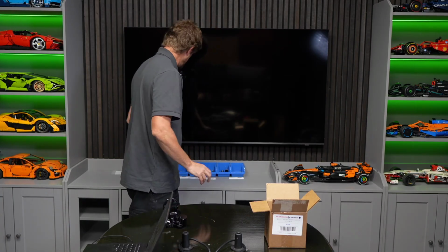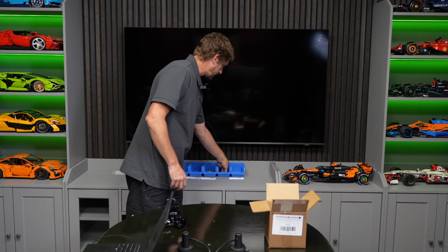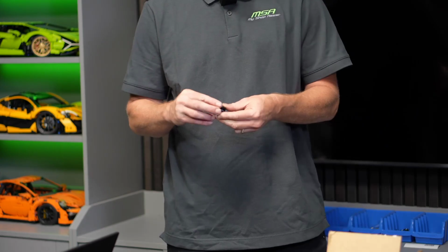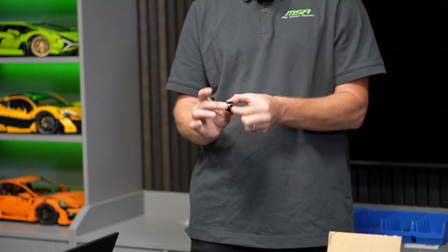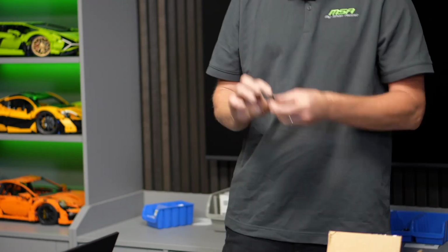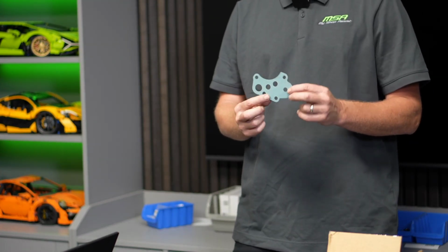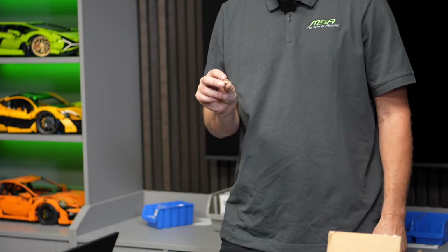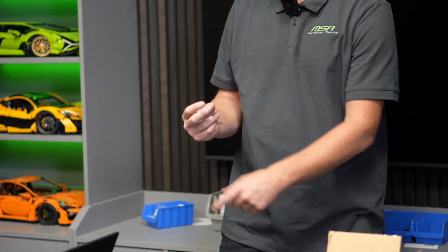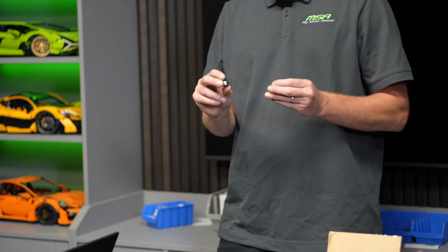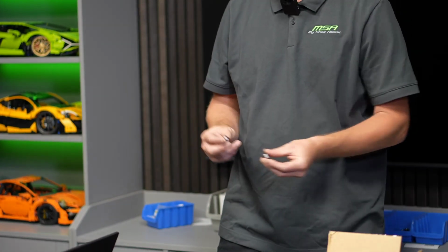From there, we've got the other manufactured components, which is this cap and the piston for it, and the spring which comes from the dealership. We have the oil filter housing gasket, a 1/8" NPT plug in case the car is for an Evo 8, we cap one of the ports for it. Some 3/8 BSPT plugs for some other ports that are optional.